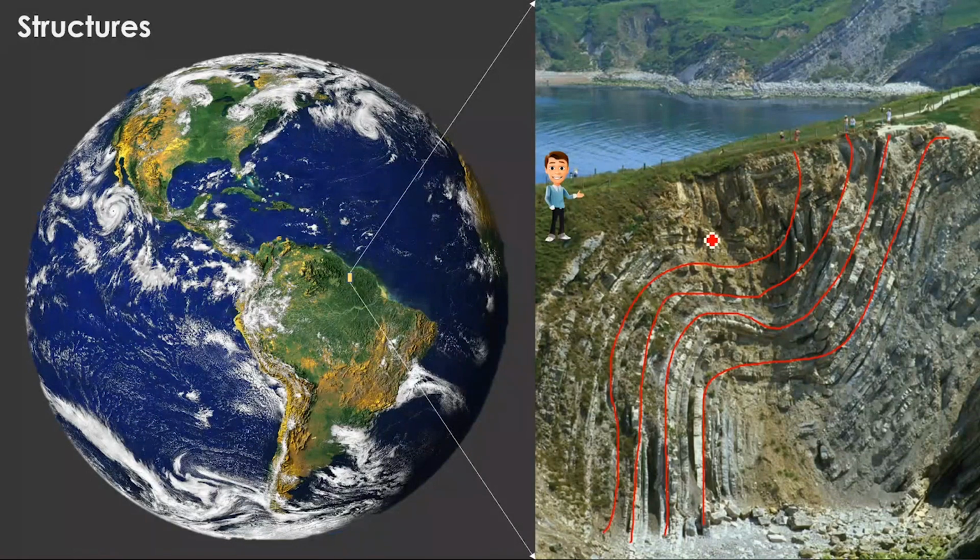Now if we imagine we are going for the same construction activity here, and I ask you to do a construction on this part, you need to make a trench, so this much part you have removed. Now one foundation is going here, another foundation is going there. Horizontally the rocks are not the same. Here the rock is very stable because the direction in which you provide the force is perpendicular to the rock strata, whereas here the rocks are so disturbed that when you put the foundation here, the rock is not going to take that load.